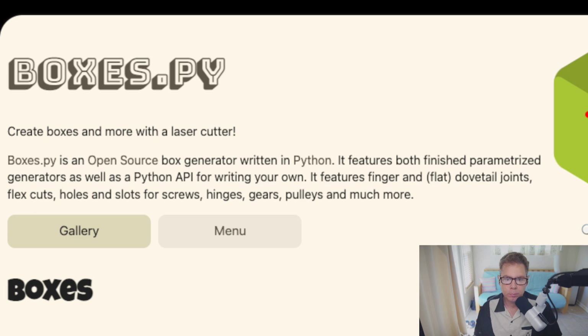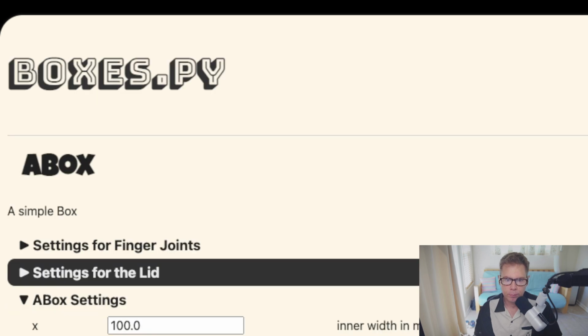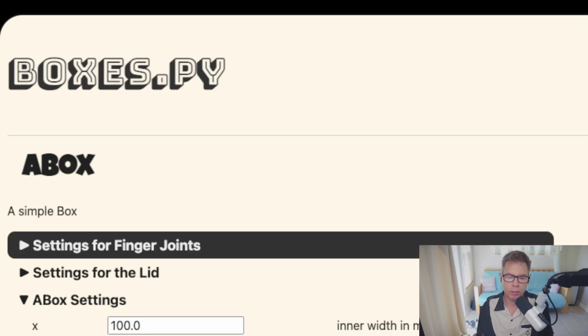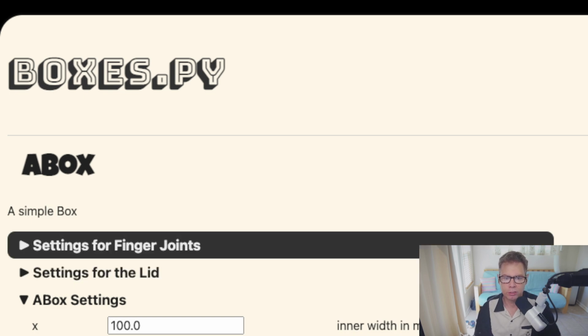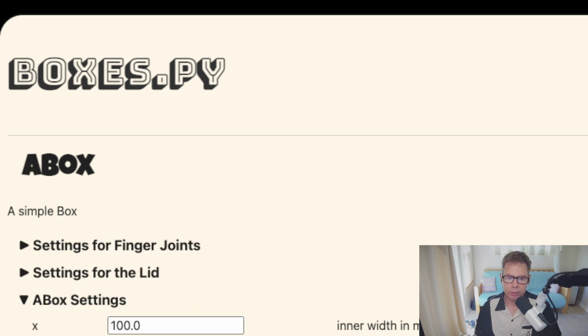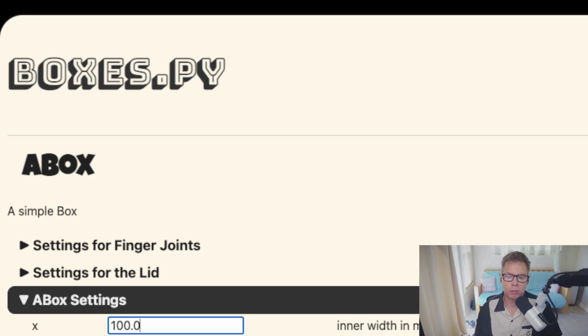And if I can pull up this, the first thing, you couldn't really see it, but it was a box, just a simple box. It's the top one that you can click, and very simple. You can put in your widths, your heights. This is in millimeters, so you have to remember it's in millimeters. You check this for the outside dimension, so you want to make sure it's got those outside dimensions that you want, or you can uncheck it and do the inside, but I always use outside, pretty easy. And you can change the bottom edge to be different things.